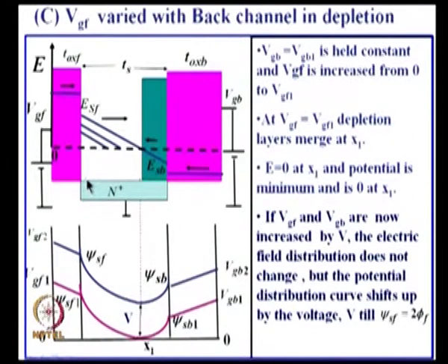But here, what is the forward bias voltage? Whatever V is there plus whatever originally was there. There is a potential here. See, just when it has depleted here, the potential here is 0. What we are plotting is just outside the surface here. That was 0, it was rising to that phi S1. But now it has gone up here. So you can keep on increasing it, so that this is inverted, this becomes twice phi f. But this should not have been inverted, because the depletion layer is narrower here. Supposing you had applied voltage so that the entire thing is at the middle, both would be the same potential, and both will be inverted. So that is the situation that you have got.